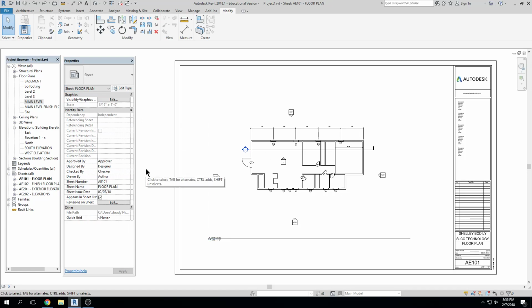It makes changes easier so that they still have a relationship between each other. When you take a view and duplicate it, you're using the architectural template but breaking all other relationships with that initial view, and sometimes you may want to keep a relationship with it. Oh, I see. So you just make a copy and add stuff to it. It's not going to transfer. Yeah, exactly.